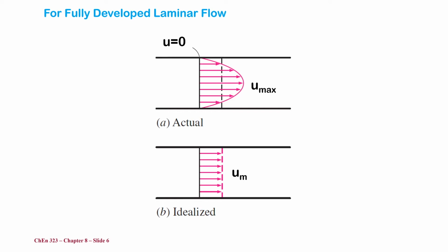In this analysis, we are going to approximate: in general, when you have a flow inside a cylinder or between two parallel plates, you have a parabolic velocity profile. So it has a maximum in the middle, it has a minimum at the walls. Because walls have a no slip boundary condition, fluid molecules stick to the wall, so they don't move, but the velocity is maximum away from the wall, so that's why you usually have this parabolic velocity profile.